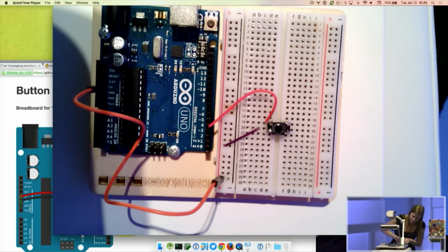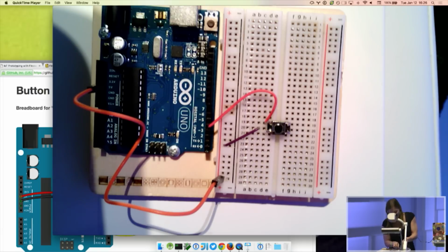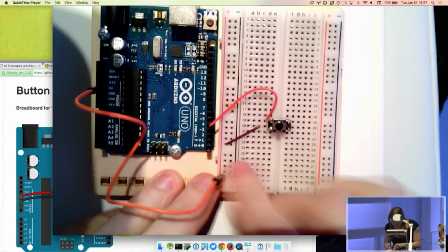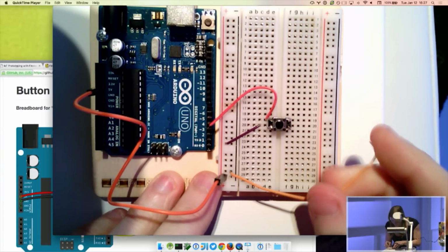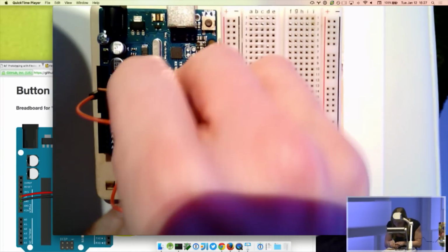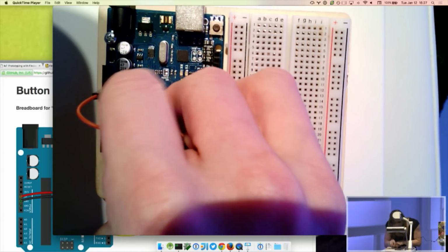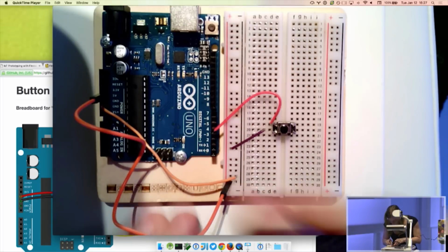But when we let go, it opens up, and it's no longer moving any state, which is bad because we have some trapped electrons that are hanging out there causing trouble. And how that'll manifest in your project is you're going to see the thing bounce back and forth between 1 and 0, which is no fun because it's confusing. So okay, that's fixed.